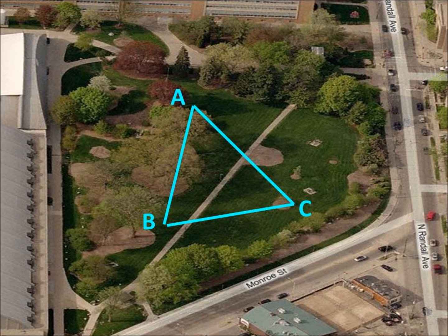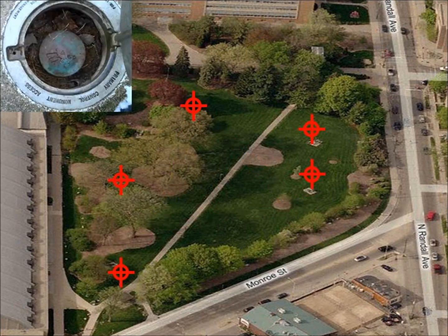In this lab, you will complete a closed polygon traverse. This method is used to set control points at survey sites. You will set up over 3 control points. One will be a known benchmark monument, and the other 2 points will be monuments with unknown coordinates. These are the monuments with the known coordinates. The benchmarks that you use will depend on what group number your TA assigns you to.